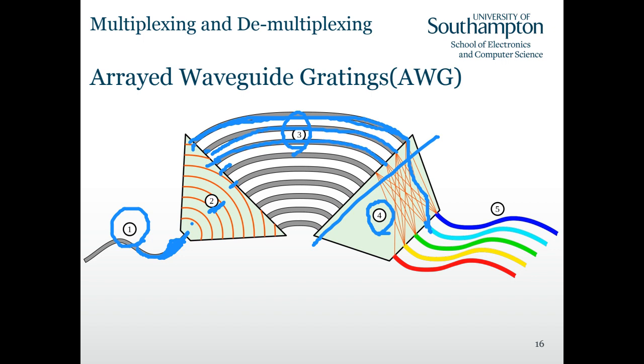All the distances before the output guide make sure that different wavelengths travel different distances, and they only constructively interfere at one output port for one wavelength. After the output port, we cannot see a rainbow signal, because optical signals still use the spectrum below visible light. But it's kind of like a rainbow because different wavelengths are separated.